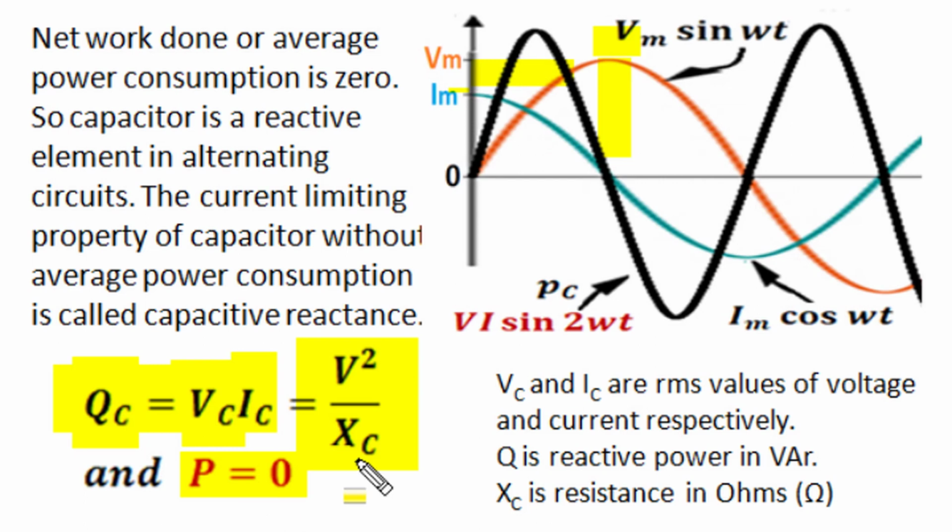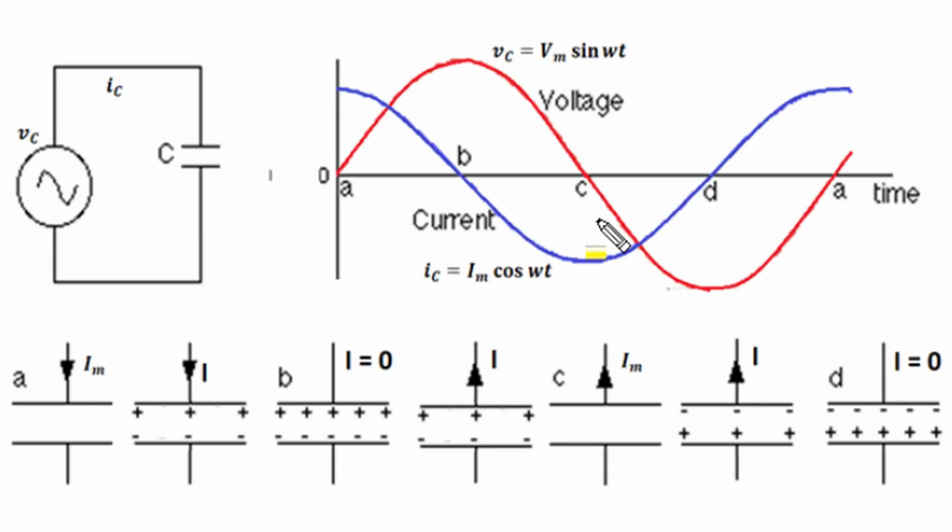is known as reactance. The best part of today's learning class is the explanation of this sinusoidal time varying alteration of voltage and current in a pure capacitor circuit when connected to an alternating supply, where current leads voltage by 90 degrees in phase. In that condition one gets peak instantaneous magnitude, the other gets zero value, and when out of current and voltage one is increasing in one or another direction, the other one is decreasing, and we can explain this behavior in 4 quarter cycles.